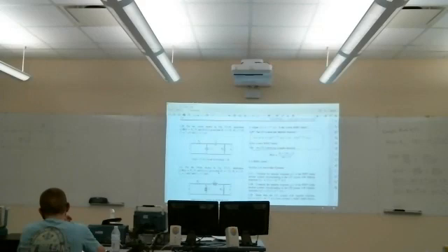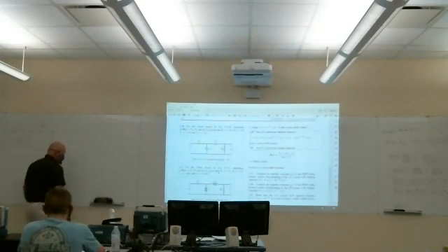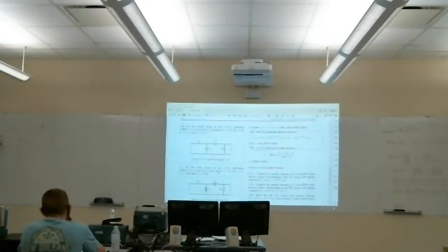This technique won't work on that, but a technique that works on these ladder type problems, which usually results in fewer equations, is to let the output voltage be a convenient value, and then work backwards to find the input. And it's the ratio that's important. We can set the input to find the output, or set the output and work backwards and find the input.